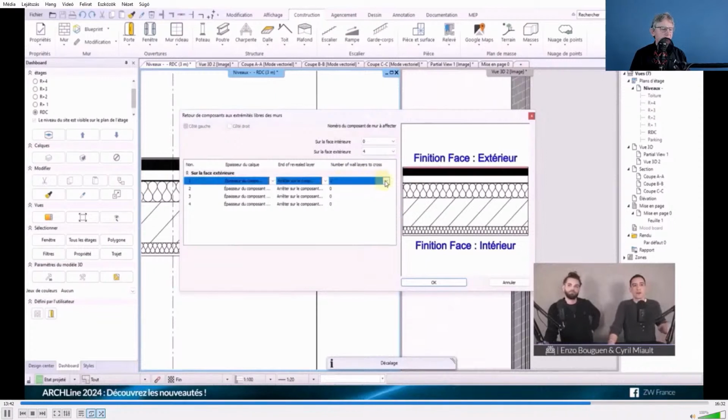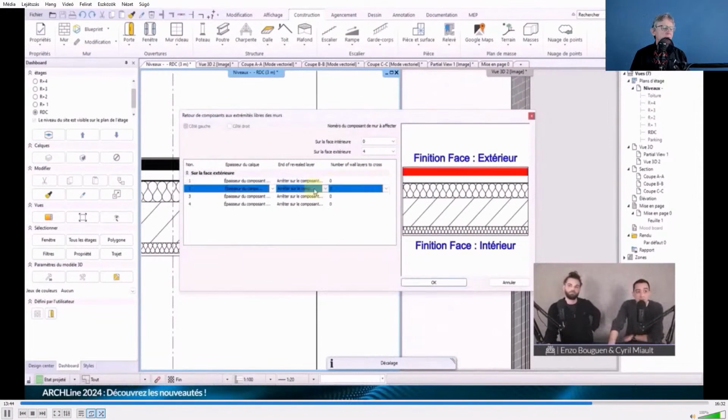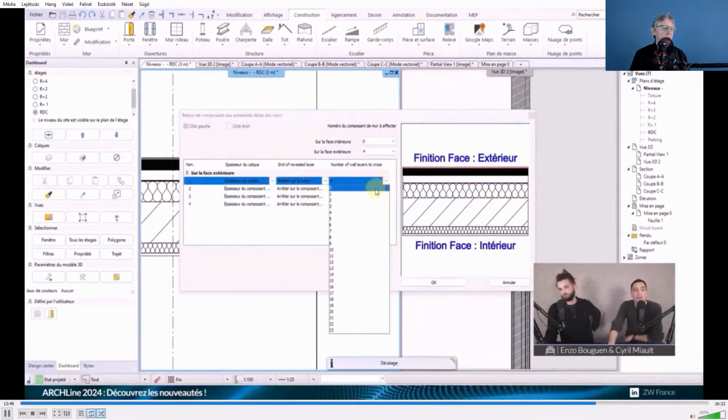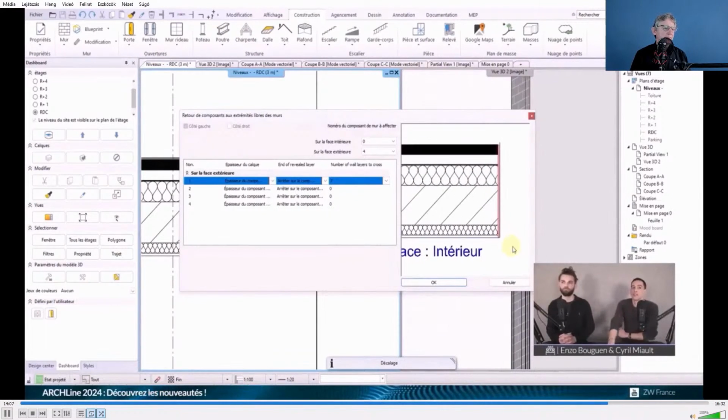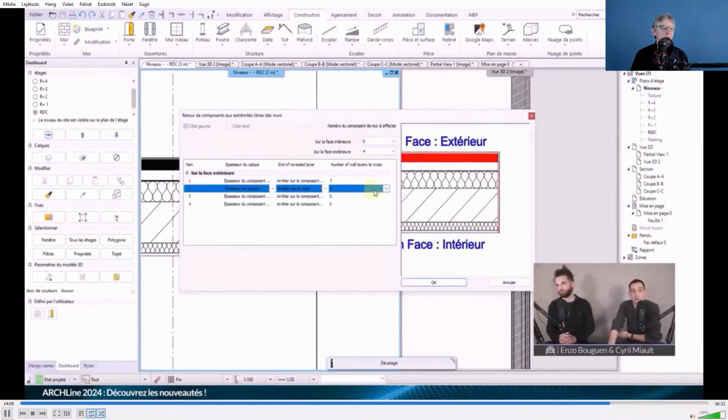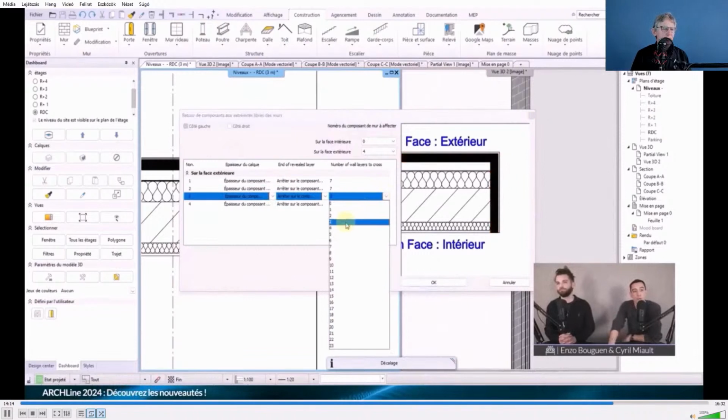Here you see that you can manage the relation between layers, so you can say which layer intersects which one, and further also you can change the thickness, or you can use the original layer thickness for the bended layers for the wrap. So in this case we set up the first one, and now let's see another case. So now we are managing 2 layers or even more until the insulation.